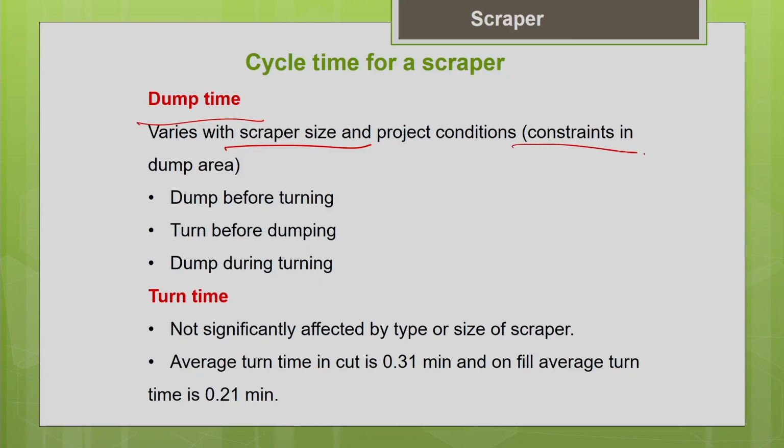And also it depends upon the constraints in your dump area. Many times you can see that the dumping site may be very narrow, and a lot of congestion of other machines will be there in the dumping site. In that case your machine has to wait for dumping. So all these things, depending upon the constraints in the dump area, can affect your dumping time.